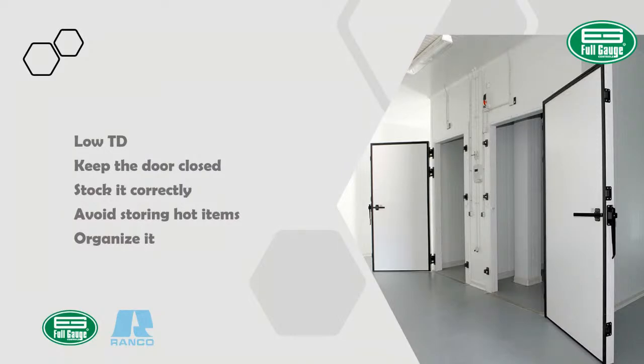Another good alternative to reduce frost buildup is the adoption of door switches. Some digital controllers feature a digital input, which allows the connection of a door switch. Based on that door switch, you can monitor when the door is open or closed, and have alerts when the door is left open or when it has been open for a longer period of time.